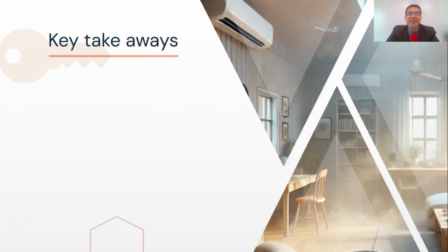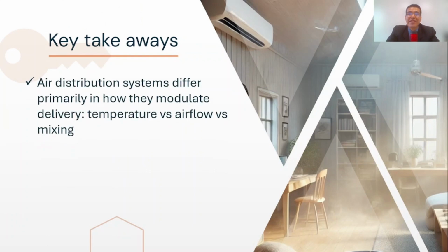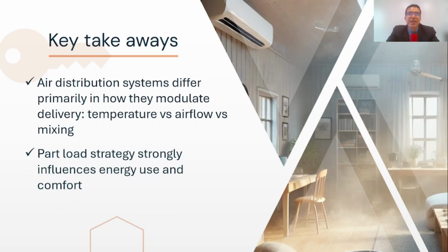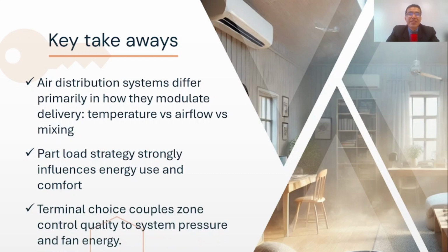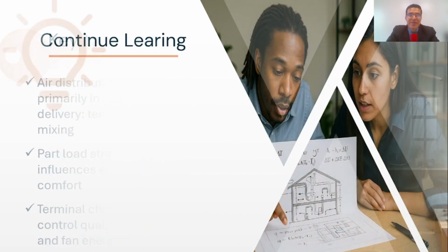Finally, for this video, let's recap some key takeaways. Remember that the control variable, temperature, airflow, or mixing ratio, defines each system's strengths and weaknesses. Most operating hours are part load, so the control strategy there dominates energy outcomes. Specify terminals with full awareness of pressure, noise, and maintainability implications.